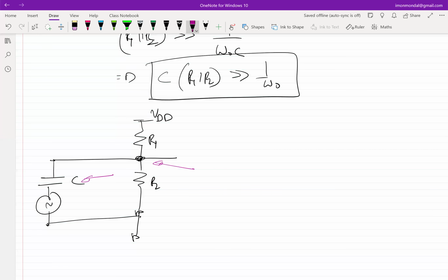If somebody suddenly comes up and tells you to use a DC blocking capacitor, don't get fazed about it. This is what it means. The second purpose the capacitor is serving is that I want this VI to appear directly as a VI across that node, which means the capacitor is acting like a short circuit to a non-zero frequency signal.